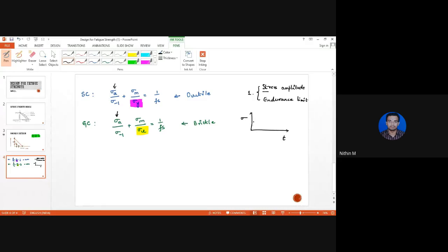At time 0, you put a load of around 60-70 kgs. Till the time you are sitting on the desk, the magnitude of force will be constant, and thereby the stress induced in the component is also constant. This is basically a static stress.